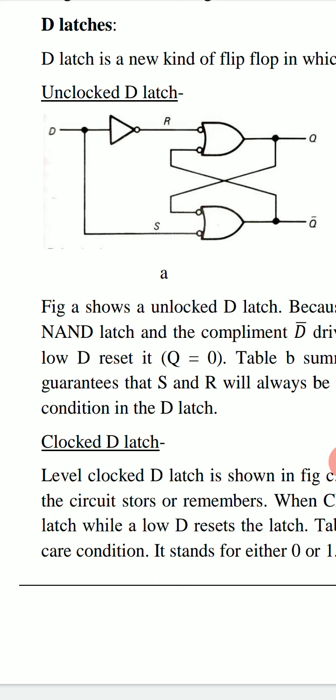This is unclocked D-latch. Input signal data bit D goes directly to S signal of lower NAND gate, and D bar goes to R signal of upper NAND gate.